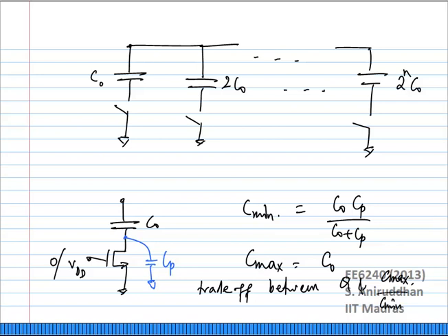Assuming that the power supply is maybe 1.2 and it tunes over 1 volt, right? So with a single varactor for each step, you can tune 30 megahertz. You need to cover 300 megahertz. You need 10 coarse tuning steps. That's clear, right? And among those coarse tuning steps, when you turn on and turn off these switches, you need to make sure there is overlap in the fine tuning, right? Otherwise, you might find a dead band where the PLL may never lock, right?